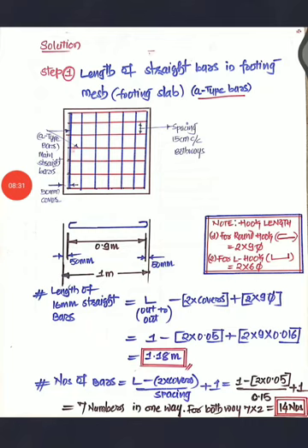Now here you can take the 1 meter by 1 meter base slab size, and it will have a cover of 50 mm on both sides. It is very easy to determine the straight bar. The outer distance is 1 meter, as I have shown here. Then deduct both side covers, 50 mm and 50 mm. Then you are supposed to add 2 hooks, on both sides. Those 2 hooks will be 2 times 9D.